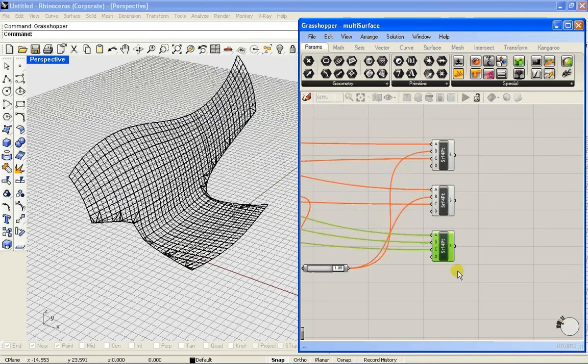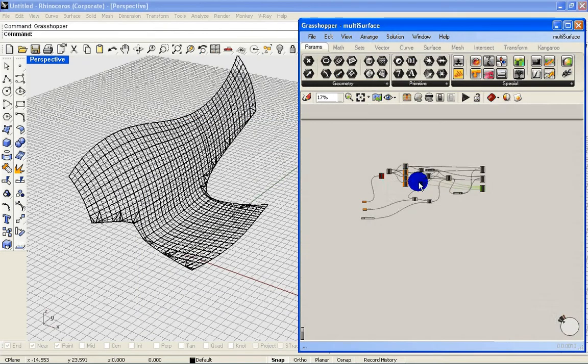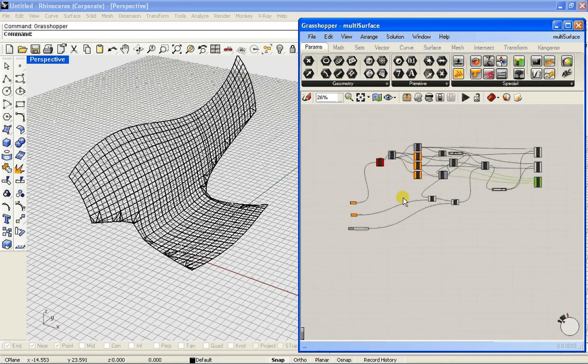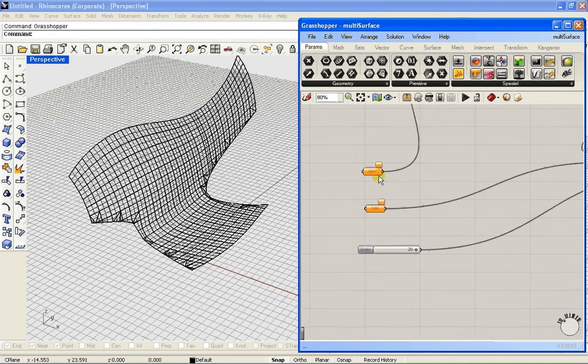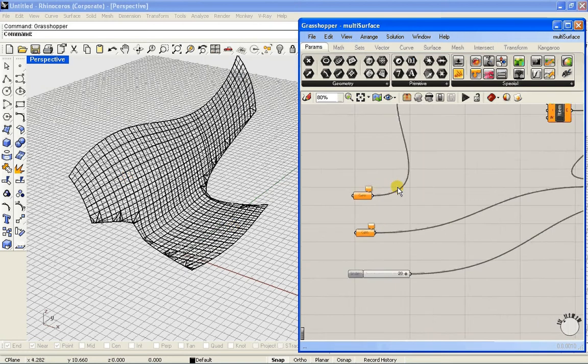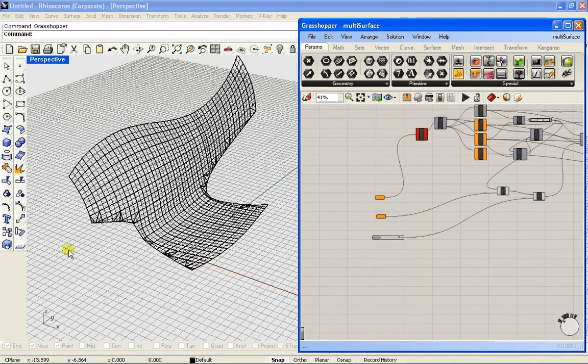And this is pretty much a very simple script in Grasshopper. There are two inputs here on the left. One is for the geometry, and there's another one where we're going to generate a point, which is going to establish a relationship of distance between the point and each quad, to generate afterwards a corresponding geometry in each of those NURBS surfaces.